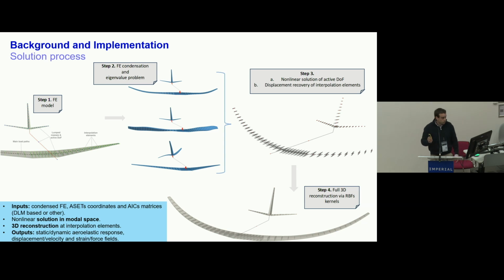Okay, so very quickly, the solution process, just to give you an overview. We start with a linear FE model. We condense it into the main load paths, where we apply the aerodynamics. We extract the linear modes. Now we solve these nonlinear equations on the reduced model, and then we can compute the full 3D reconstruction of the displacement field, stress field, and so on.